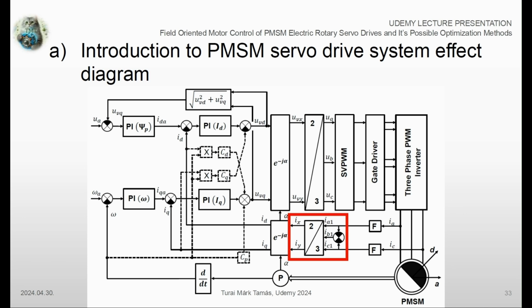By utilizing the Clarke transformation, we shall calculate the current components in the XY coordinate system. This coordinate system describes the measured three-phase currents as a time-variant two-phase current system. During the Park transformation, we are going to use the actual electric angle of the rotor pole flux as an input to calculate the actual direct and quadrature currents present in the system.